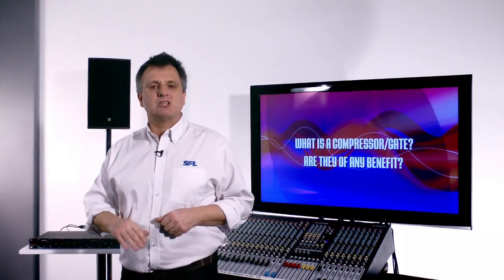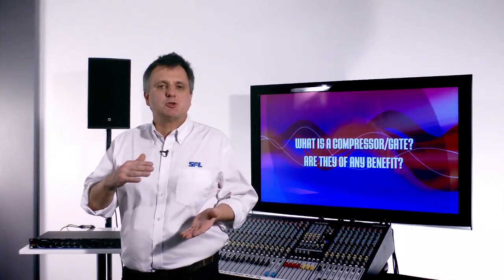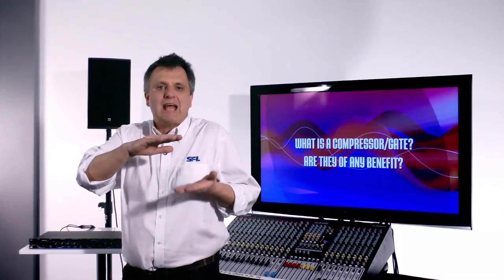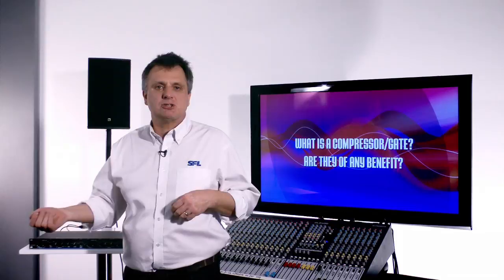The role of a compressor is twofold. First of all, it's there to maintain the reduction of dynamic range so that we don't have any big spikes between what is normal, what is the average level, and what will be the peak output of any particular voice or instrument. The other role that a compressor helps us with is it keeps the dynamic range of signals within the capabilities of our own PA systems.